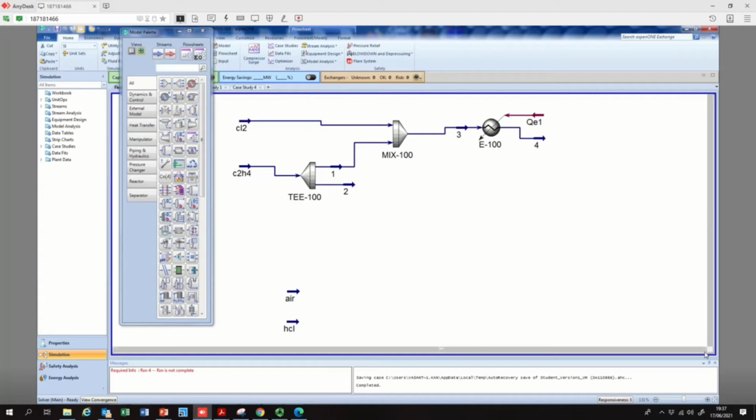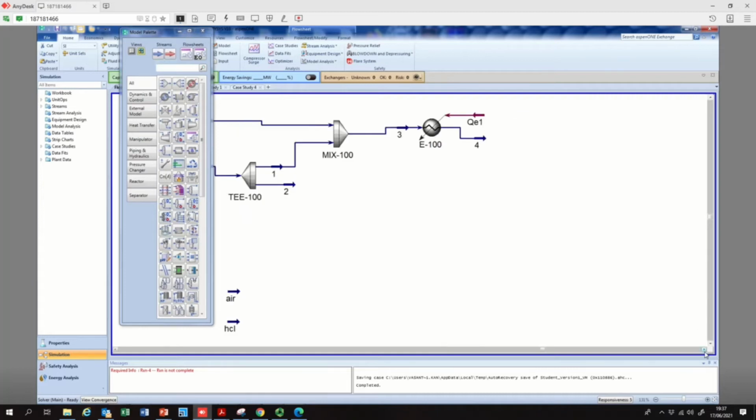For your project, especially for this particular module, you need to submit a project for which you have to use Aspen HYSYS and try to get the kinetic constants from the literature. And if something doesn't work, then use this type of conversion reactor.